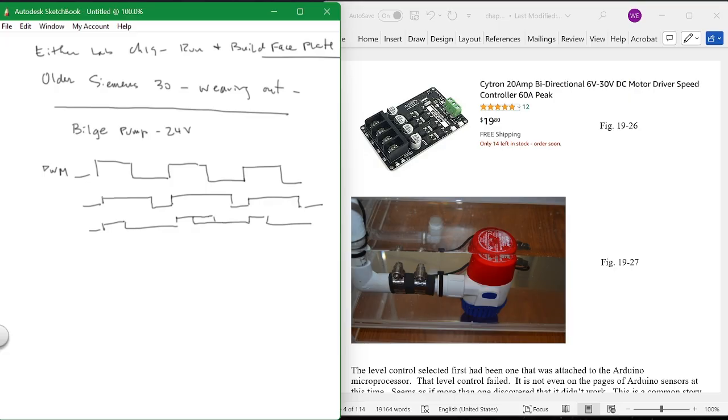Now, the dark side of this is that pulse width modulation creates harmonics. And there's a capacitor in here, and the capacitor with harmonics will heat up. But because it's underwater, the water cools it, and usually it runs pretty well. If you run this thing dry, this thing gets hot. So please don't run it dry or run it very long.